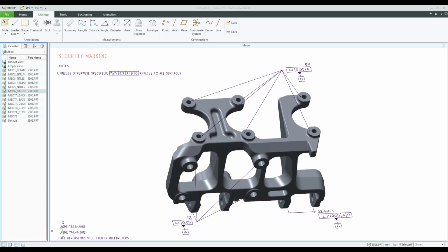So the next question, can you view the annotations in the part in Creo View by just opening the part file versus exporting the PVZ file? So no, all that information is not going to be in the part file. That PVZ file is a specific file type, and that's how we take all that information and sort of export it to a different program that's accessible by a lot more users, if you use Creo View Express. So that's why we need the PVZ version in there.